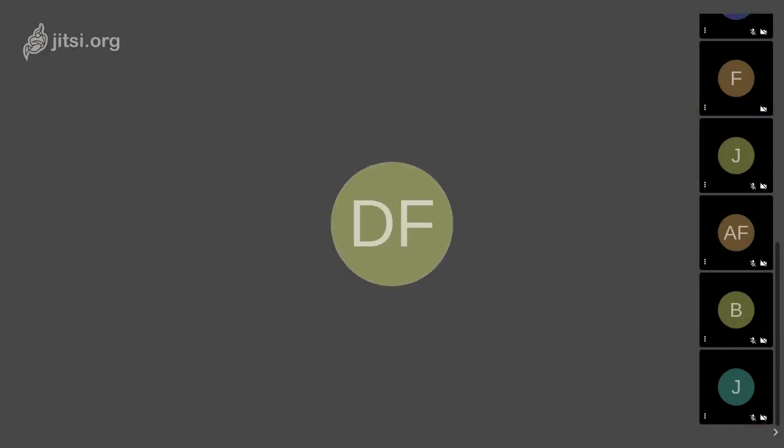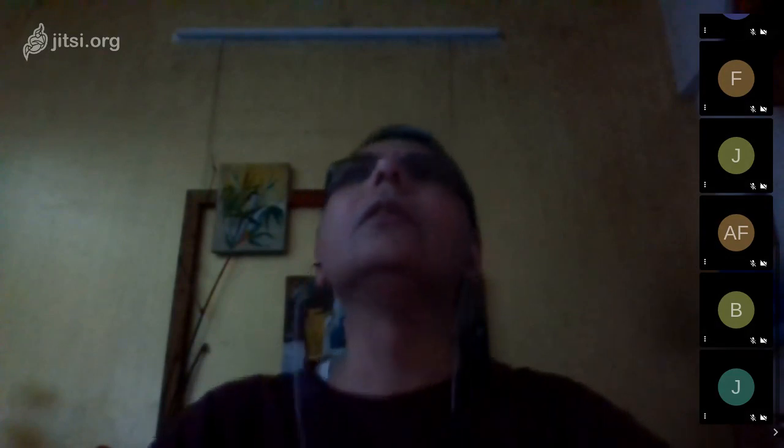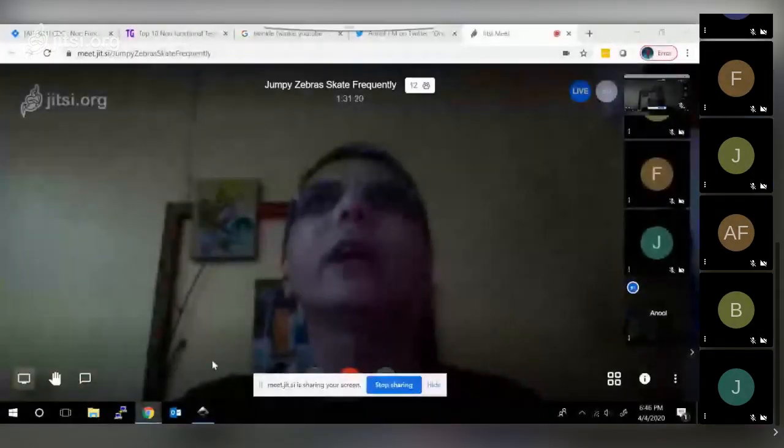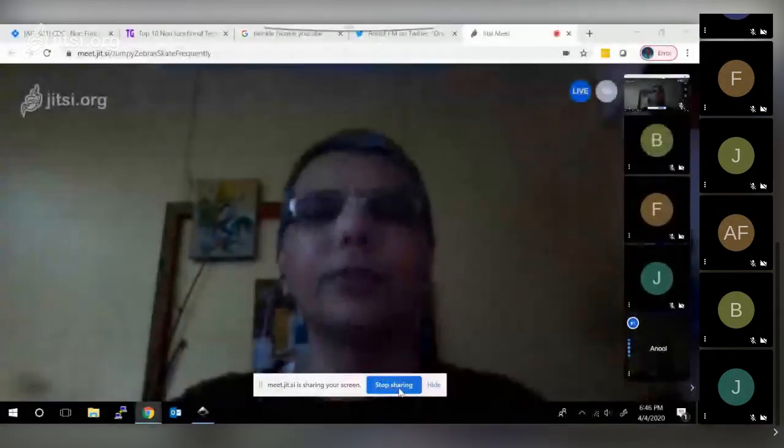Anil, what would have been the correct way to do the outline? Let me think about it. I would definitely do it using the KiCad primitives, so arcs and lines within KiCad. I would use the DXF import as a template.